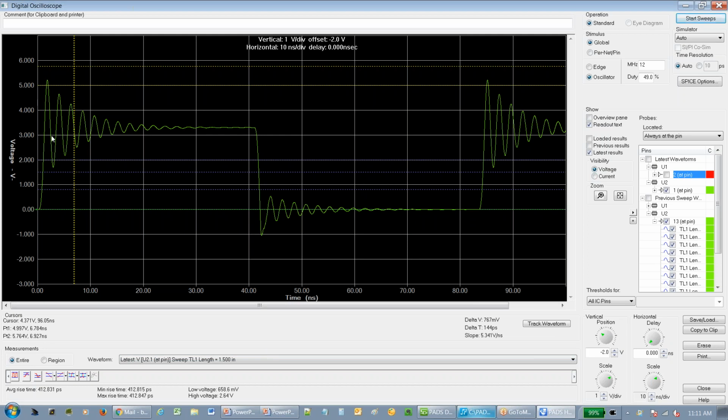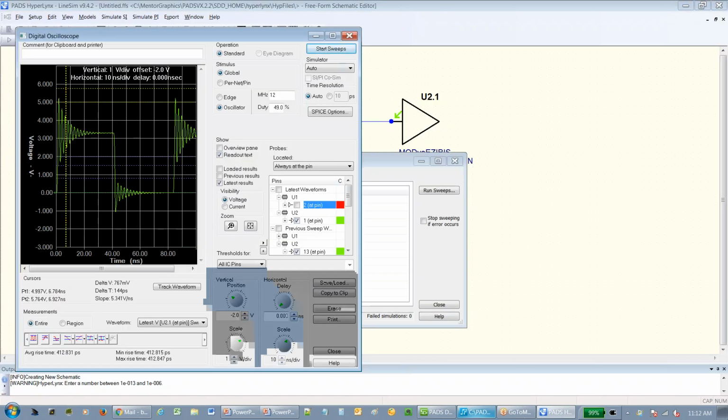I'm switching at 12 megahertz, but this design is definitely not going to work. One, I'm driving to that 5-volt rail limit, plus I'm inducing a lot of high frequency in my design. I've got signals that are actually crossing the switching threshold, which would cause time delays or data errors. So again, these are the things that you really need to think about when you're designing your products.